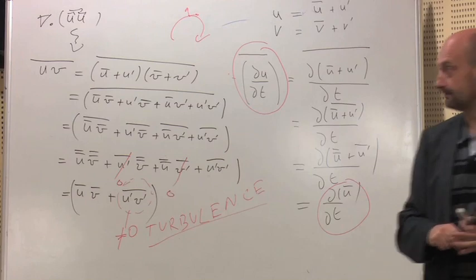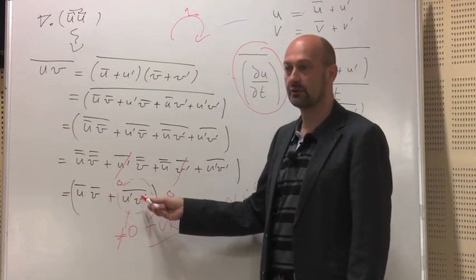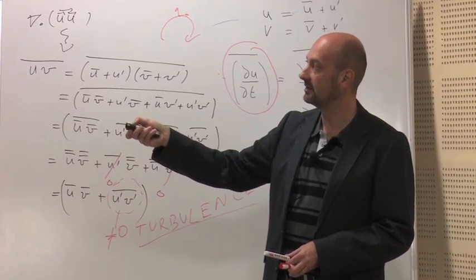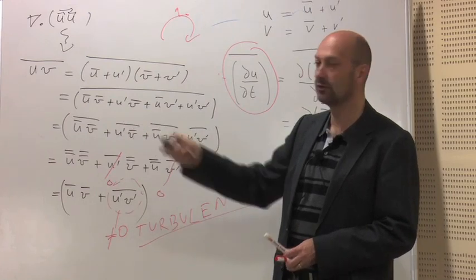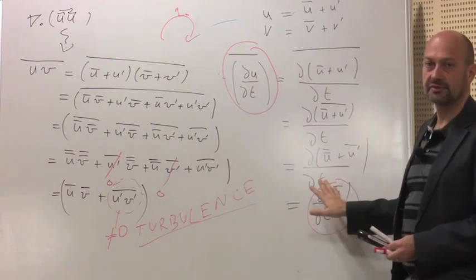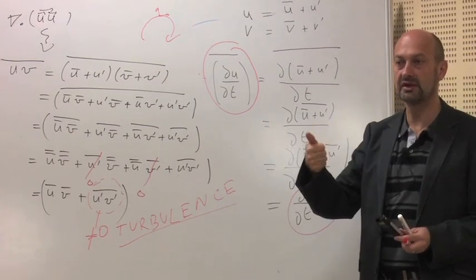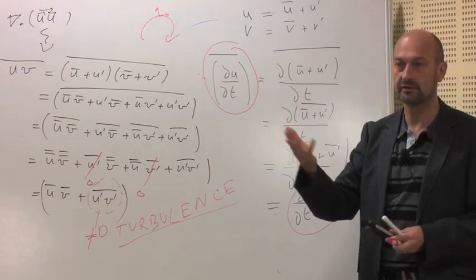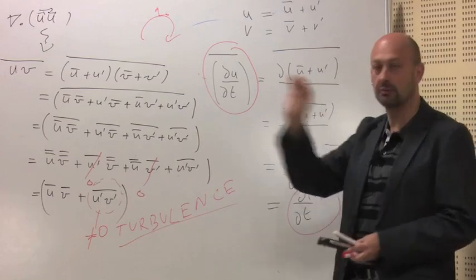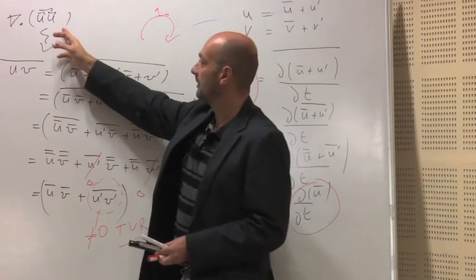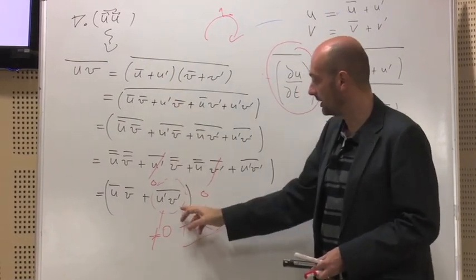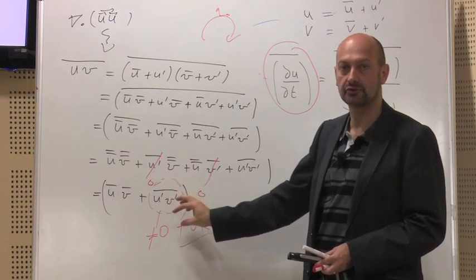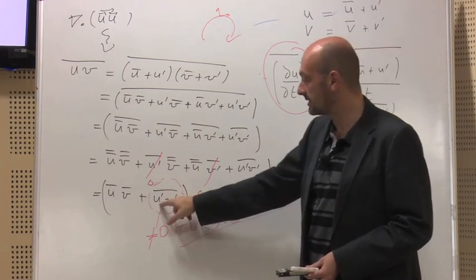The problem is, you see that in the Reynolds averaged Navier-Stokes equations, so we call them RANS modeling, in these new equations, all the linear terms will be exactly the same. So du by dt, gradient of p, Laplacian of u, gravity, of course, gravity is constant. So all these terms will be exactly the same, you just have to add a bar. But the nonlinear term will generate new objects, new terms in the equations. And the problem is that we don't know them.